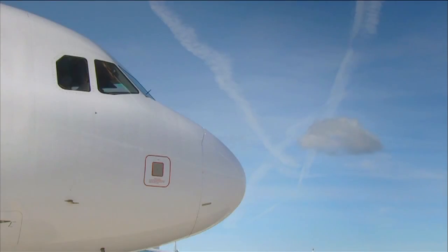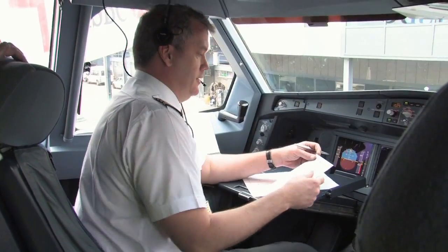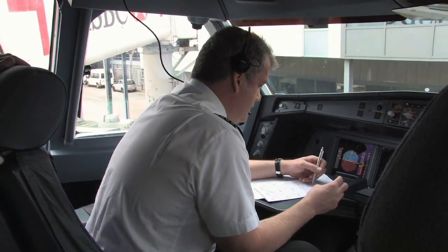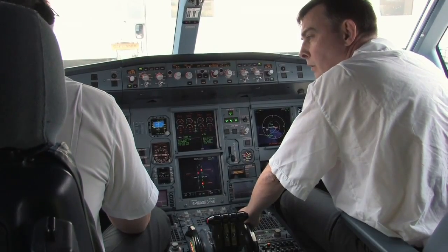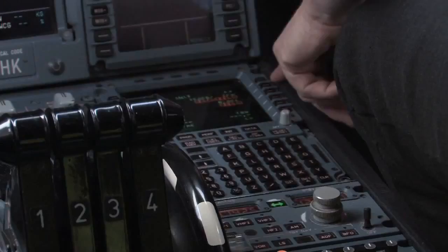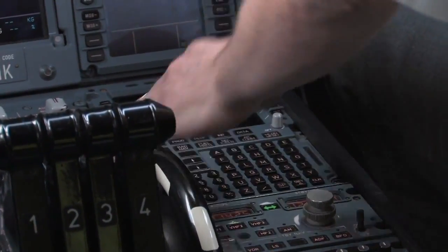In the flight deck, crews can also play their part. When you receive the load information, take time to read the figures. Don't just take it for granted that they are correct. Use all of the information available to you to ensure that a gross error has not been made.